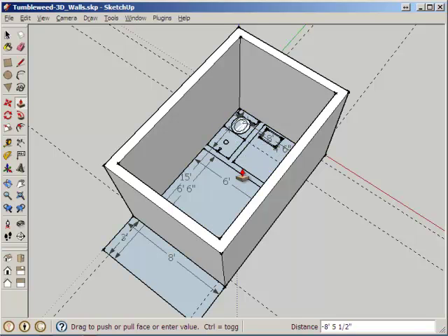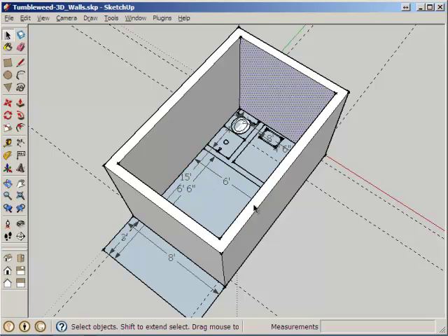You can, in fact, under some circumstances, push it through and to the other side, but if you look in the measurements box, it says distance is -8 feet, and so that brings the thickness of this central portion to 0. If I click now, it actually deletes it, so there is in fact no surface in here that belongs to this set of walls here.